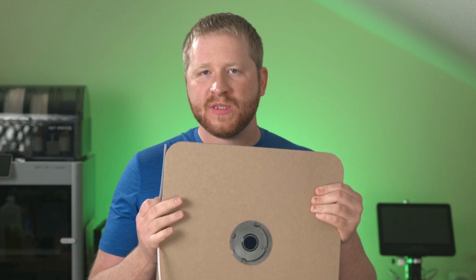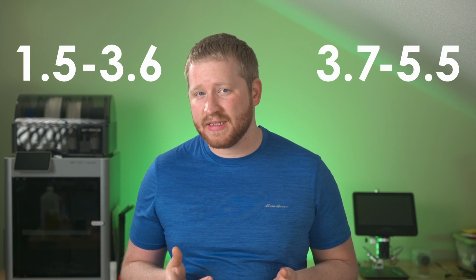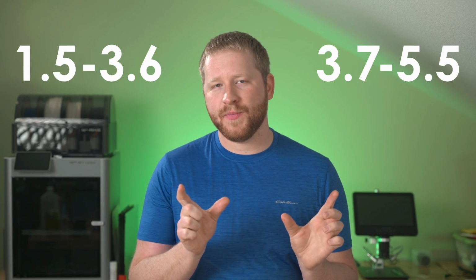Some other little details. To join the PCBs, I'll be using ribbon cable. I ordered a full spool of 26 gauge 4 conductor from 3M that is only about 2/10 of an inch wide. I'll strip the insulation and solder it directly to the PCBs. There was a slight issue with voltage levels. The microphones want 1.5 to 3.6 volts, whereas the LEDs specify 3.7 to 5.5 volts. Notice that there's no overlap here.